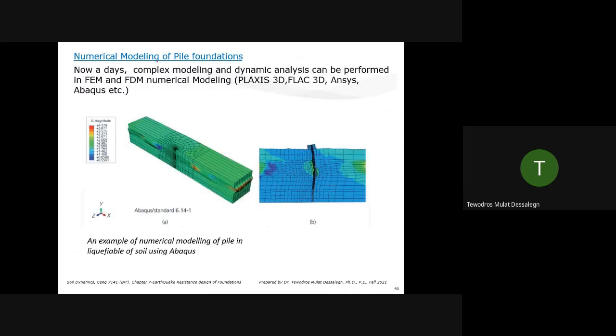Numerical modeling of pile foundation. Nowadays, complex modeling and dynamic analysis can be performed in FEM, FDM numerical modeling, Plaxis, FLAC, ANSYS, or Abaqus, any of them. They can model it. But there is some limitation. How much model size you can incorporate around the pile, that's a limitation. And they can work well for a single pile, but in reality, you may have a big building with hundreds of piles. So it gets too complicated.